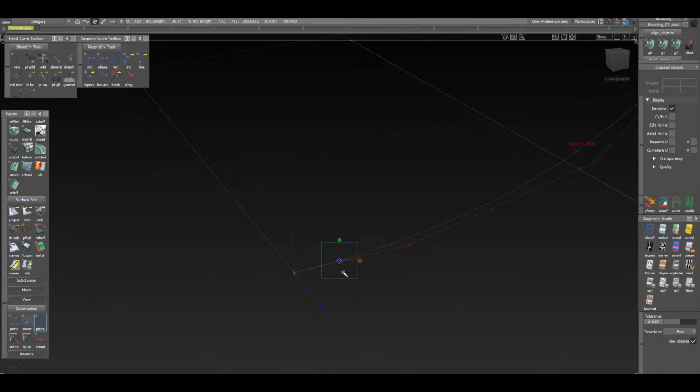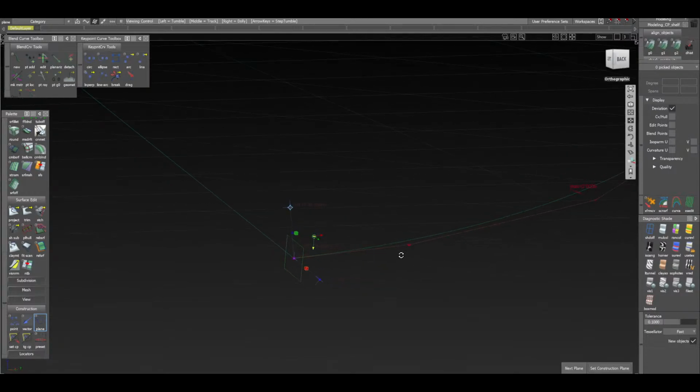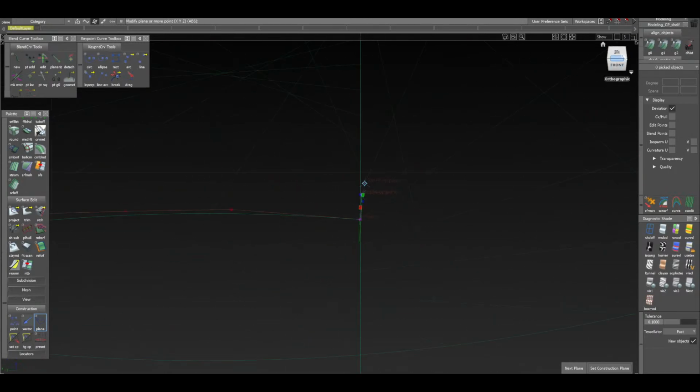I've selected the fit curve as a reference line, a reference axis, and it's blue, which is telling me that it's associating it with the z-axis. So this may or may not work. We're just going to cross our fingers and we're going to try anyway. So I'm going to drag it to the base here, and then I'm going to let go of Control and Alt. I'm going to hit Alt and Shift so that we can turn the view, and then Alt and Control, and I'm going to click the secondary axis, which is over here. Okay, and it's looking like it's associating that with green, which would be Y, and then the last one looks like it's going to be associating that with X. So that's looking okay. I think that's looking pretty well lined up.